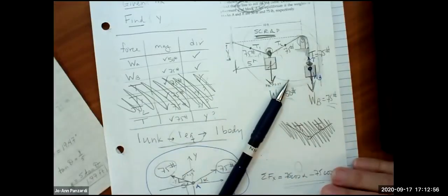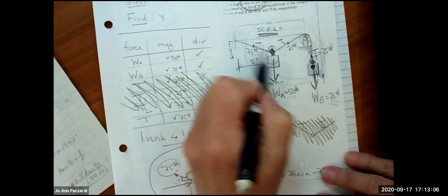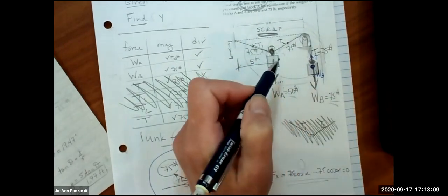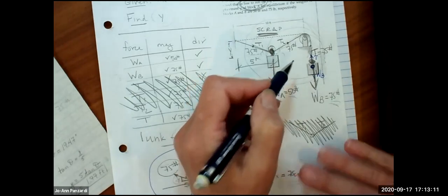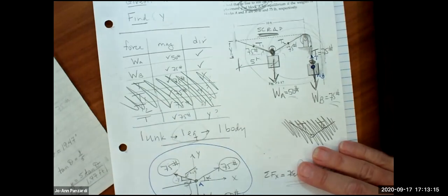So when we're looking at this problem, just concentrate. Right now, we're doing statics of particles problems. We're not doing free body diagrams of huge bodies. We are only doing free body diagrams of points to simplify it. And we're picking points. We'll get complicated in the future, but not yet. We're picking points where all the forces are converging. Okay? Sounds good.